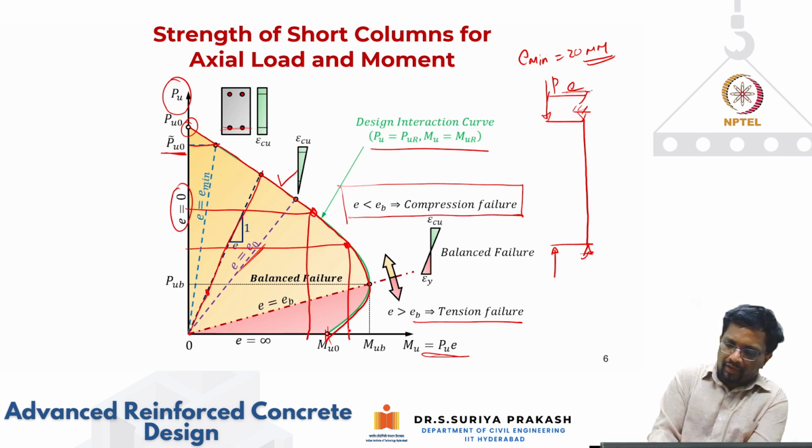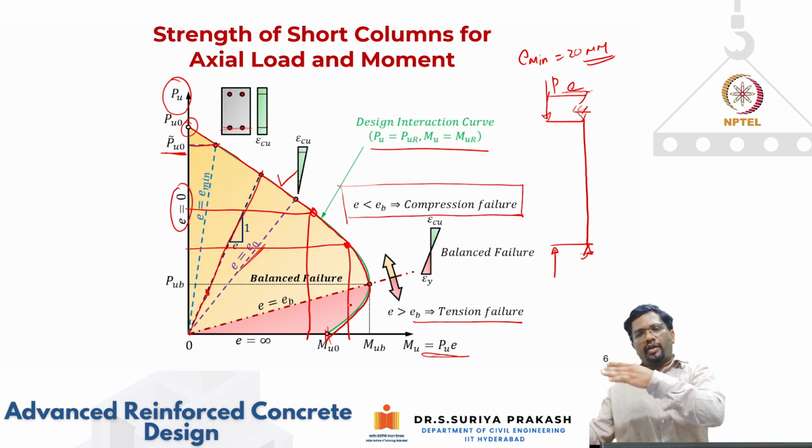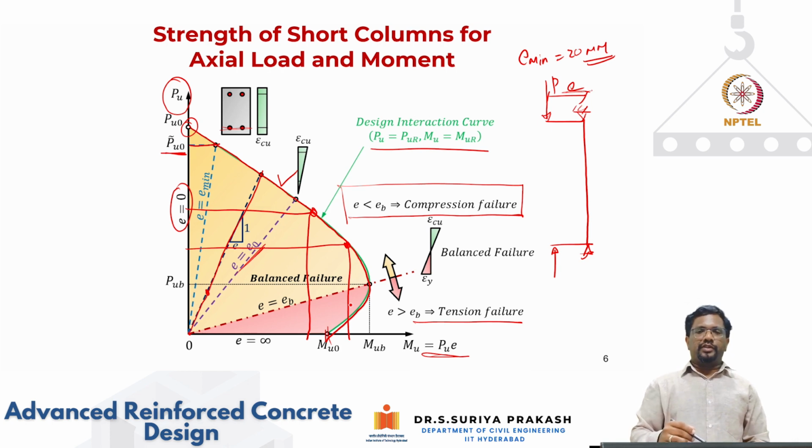I can have a high axial compression and low bending, or a high bending and low axial compression. Depending upon the design requirement, we have to calculate the capacity of the section and find out whether to increase the concrete strength or put more steel. That we need to look at.